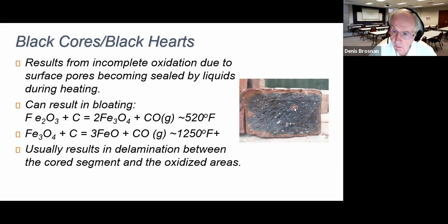So the question is, is this a defect in the brick? And it's not, because it's allowed in brick standards. One problem that can develop is you can get a delamination here between the high carbon area and the red oxidized area. If we have cracks formed here, there's some delamination. In my opinion, there could be a problem with these bricks in service.